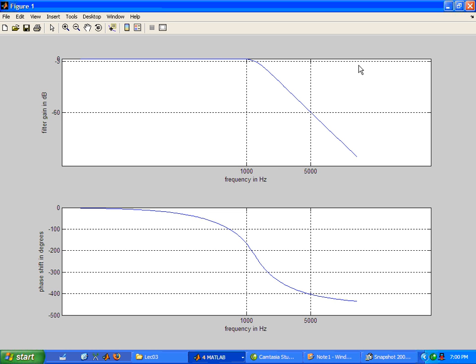All right, so you can see the shape of the Butterworth filter. One of its qualities is that it's totally flat in the passband, whereas the other filters don't have that. The price you pay for it is your roll-off could be much steeper if you use one of the other filters. But in the passband, it's totally flat. So all my frequencies in the passband will get amplified by exactly the same amount, which is a very desirable quality, again, depending on your application.